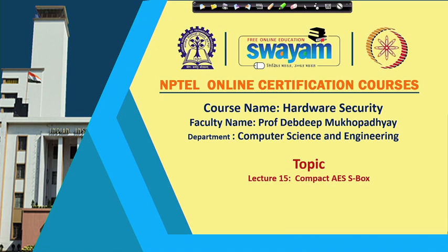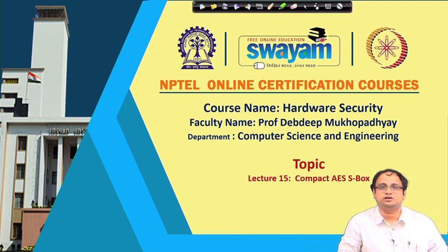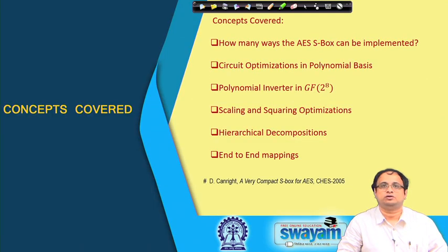So, welcome to this class on hardware security. Today, we shall be trying to look into a specific block of AES, which we have already been referring to as the AES SBox or the sub bytes. So, we shall take a closer look at the AES SBox and try to see a very interesting work about how you can design a compact AES SBox on hardware.